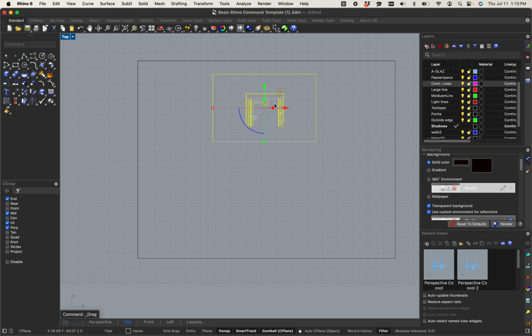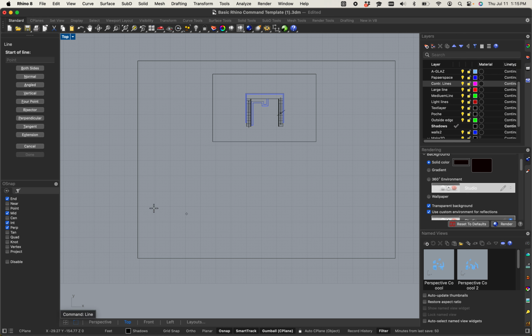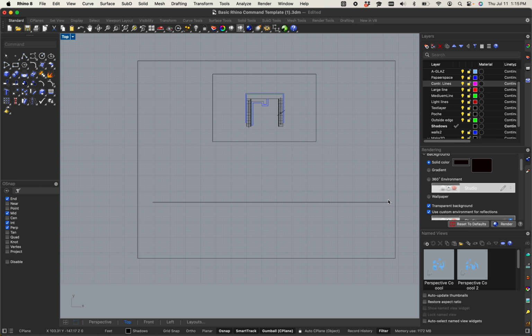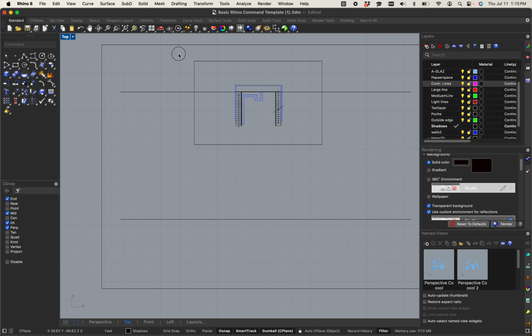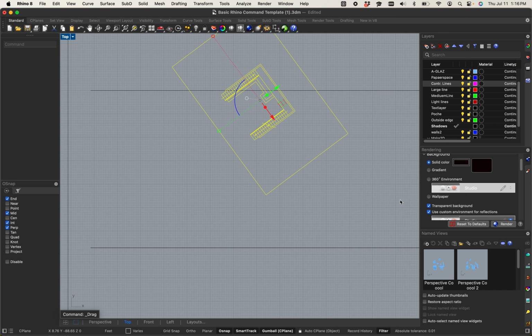And in fact, sometimes I'll even group it just so I don't mess up those lines. And in my case, I would need another drawing, the section or the elevation, so that I can get some of those lines and produce them. Now, just like a regular drawing, I'm going to have my horizon line, I'm going to have a power, perspective plane line, and I can even start to rotate, in my case, the drawing, so that I could start producing my 2-point perspective.